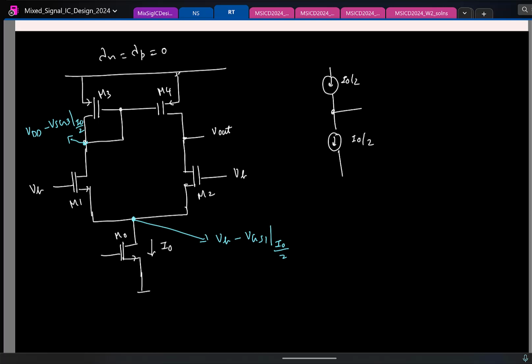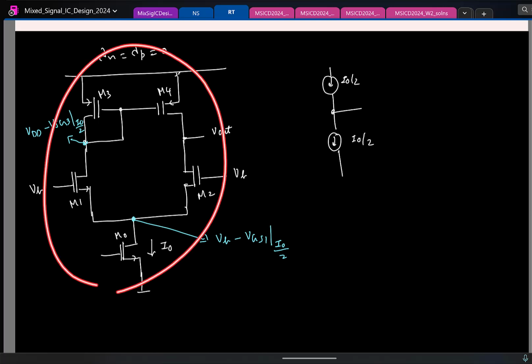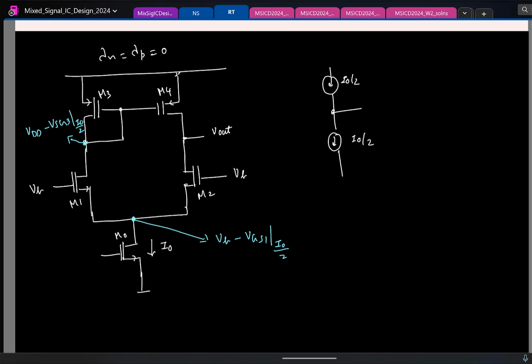Remember that finally an op amp is not supposed to be used in open loop at all. Why on earth are we designing op amps with infinite gain? What is the reason to design op amps with very large gain? To be used in negative feedback, to make feedback circuits, and the moment you have it in negative feedback,